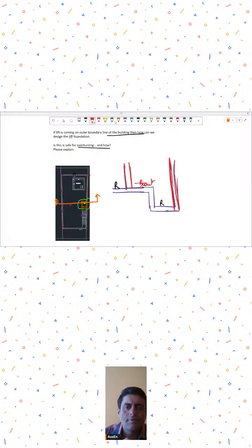So you will have to provide deep beams like this, all around the periphery of the lift pit. And over here, maybe you can also add a wall in this portion, and these are your walls, because this was 1500 mm below the main basement raft level.